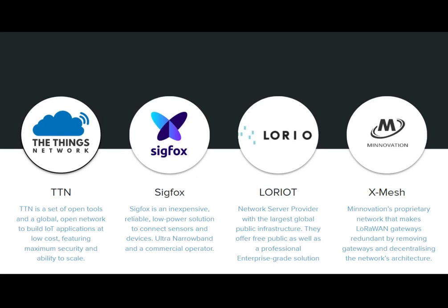And coverage is also an important factor. The TTN is available in approximately 100 countries in both public and private configurations, whereas Sigfox provides scattered coverage in approximately 45 countries. So to bring things back to the context of this video, the Northern Melbourne Smart Cities network project, the TTN was chosen due to its best fit on packet size and the pseudo adoption of the Smart Cities protocol for Australia.